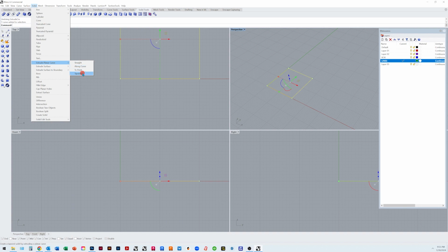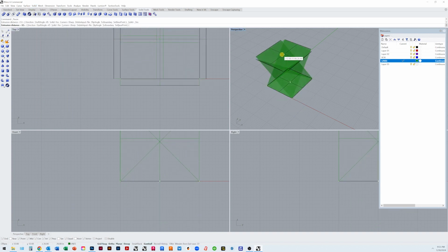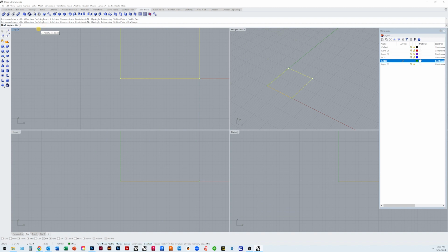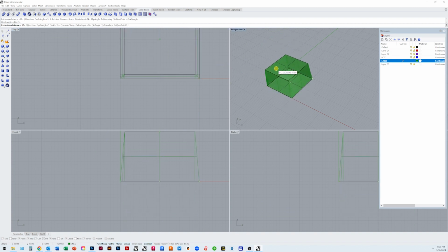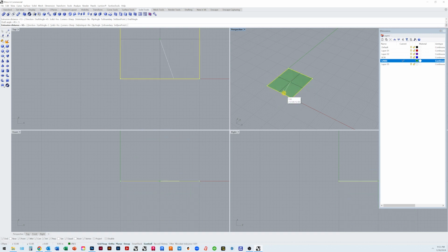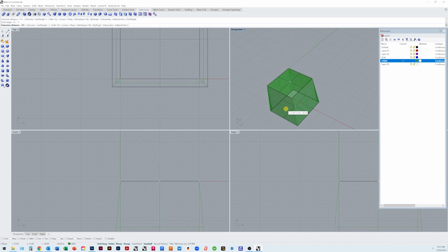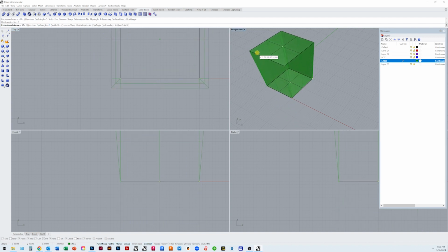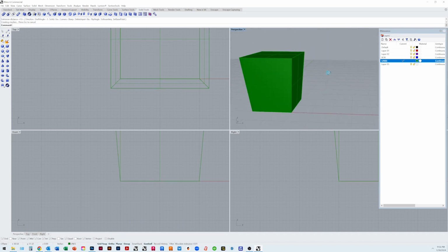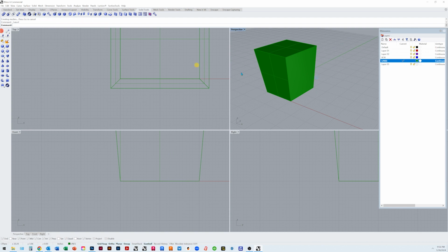Let's just jump to tapered. Instead of extruding straight, it can actually extrude at an angle. In this case, that angle's at 45, but let's do something a little more subtle. It's at 5, so you can see it's tapering it down. We can also make that angle a negative number. So if I do -5, and extrude up or down, I have a tapered shape.